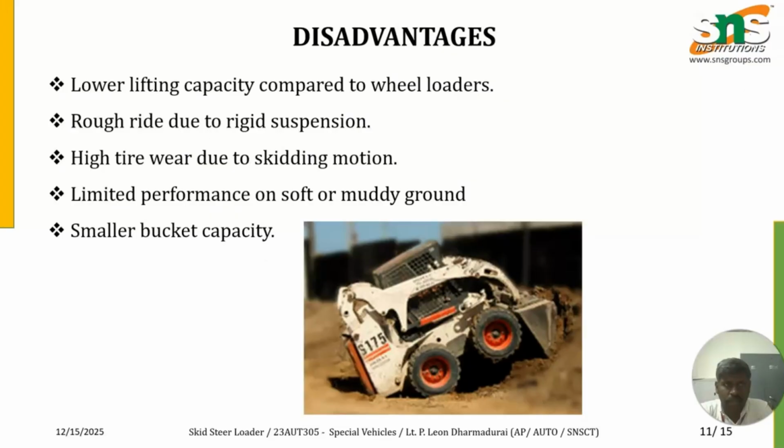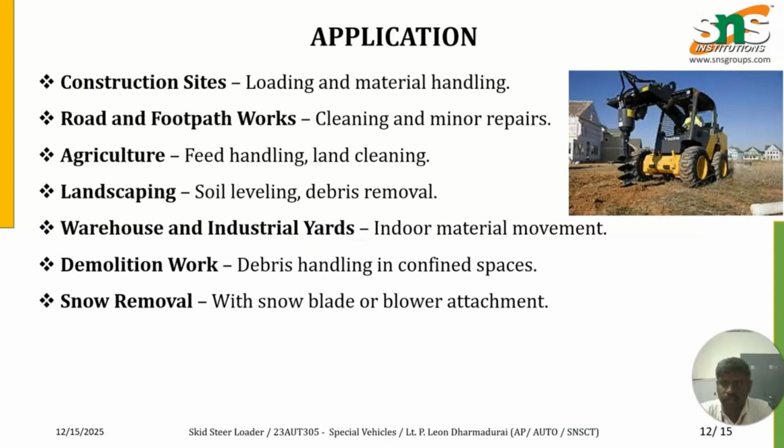The disadvantages are lower lifting capacity when compared to heavy loaders, a rough ride due to rigid suspension, and high tire wear due to skidding, because the differential steering system is followed here. There is also limited performance on soft and muddy ground, and a smaller bucket capacity, so a smaller volume of loosened materials can be taken, which is a disadvantage because other loaders can take more volume.